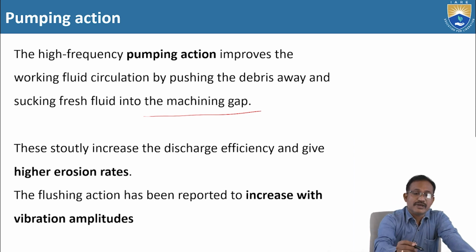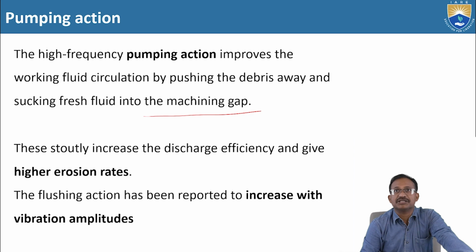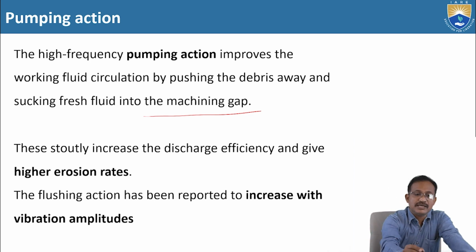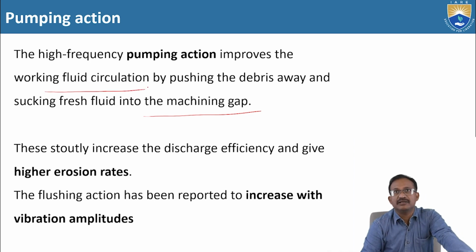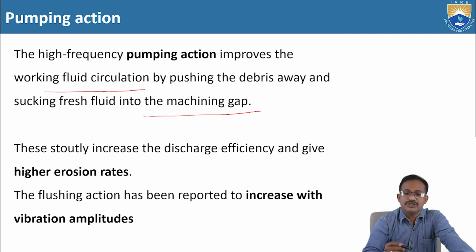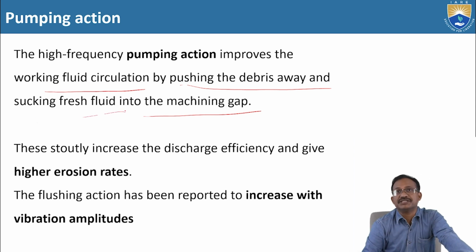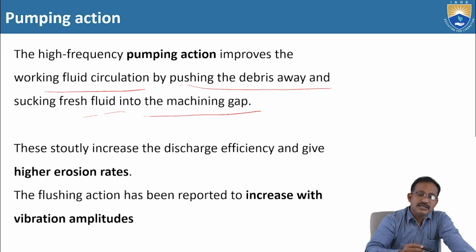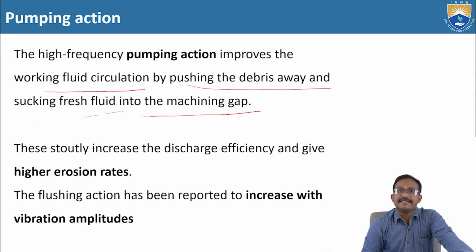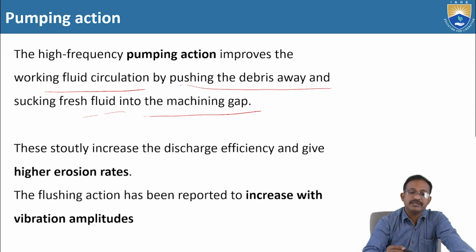Because of this high frequency pumping action, it improves the working fluid circulation by pushing the debris away and sucking fresh fluid into the machining gap. This increases the discharge efficiency and gives higher erosion rates.